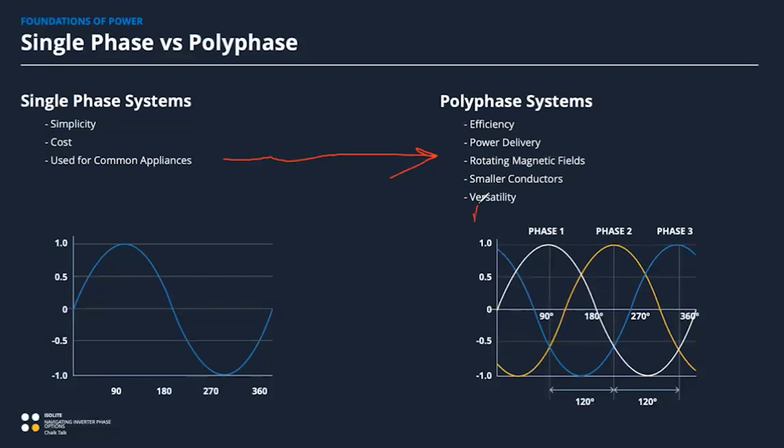So if you look at this drawing here, this blue line mimics the same one that's over here on the left side, but now there are three of them, and they happen to be offset perfectly 1/3 away from each other. The net result of that is that you always have some power available, no matter where you draw this line, either phase to phase or from phase to this zero mark, which we'll talk about here. You have power that can be delivered.